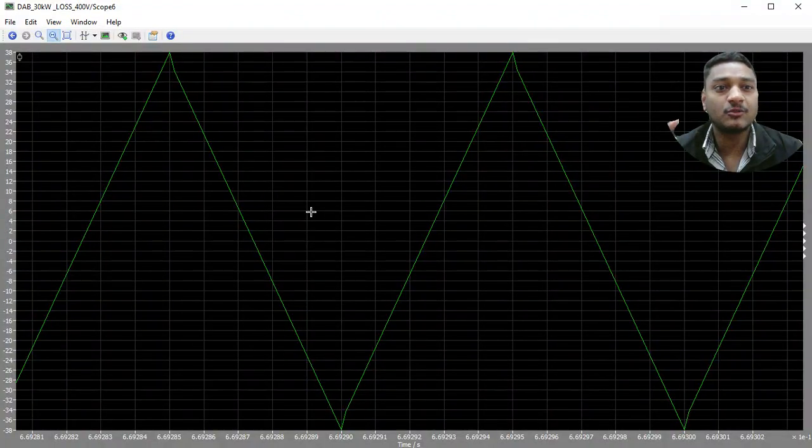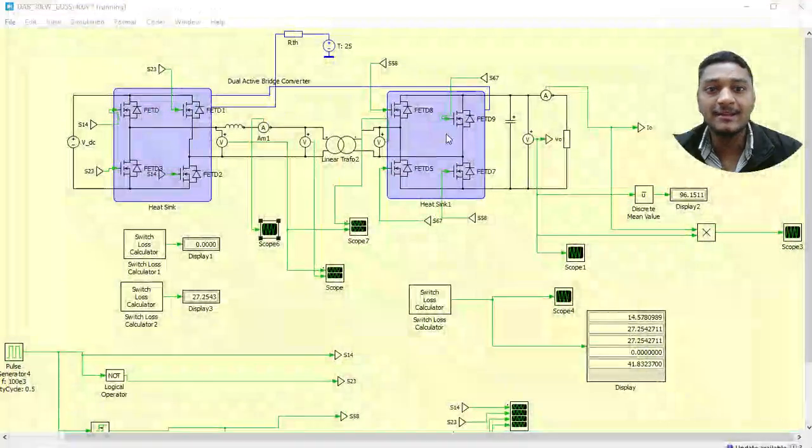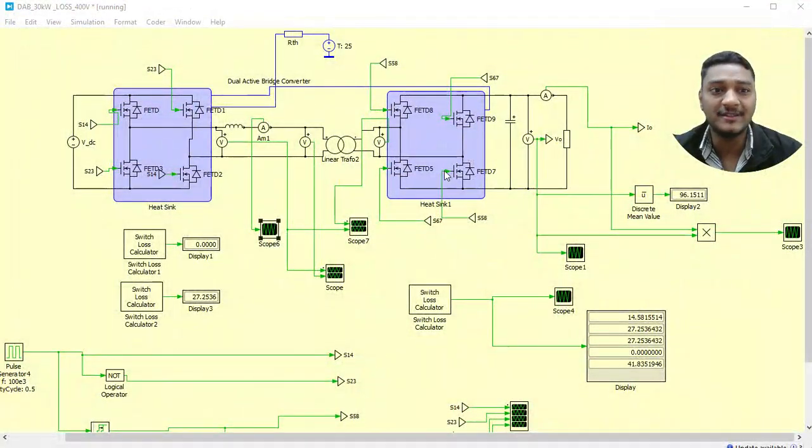Okay, turn on. So what is the direction of current IL, positive or negative, for which particular switch to turn on? So during the on of which switch, what is the direction of the current IL, that determines whether the ZVS happens or not. And we have taken this example as well, and there we have discussed why the secondary switch, secondary bridge, has non-ZVS. So those things we have already covered.